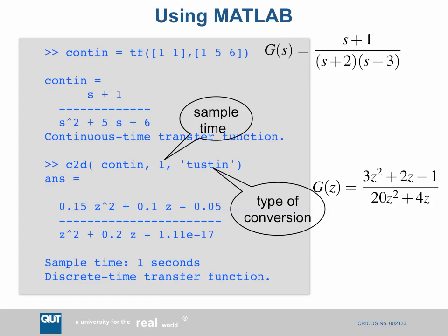So, actually converting from the S domain to the Z domain can be done by MATLAB for the case of a Tustin transform. So here is the MATLAB code that you'd need to do that.